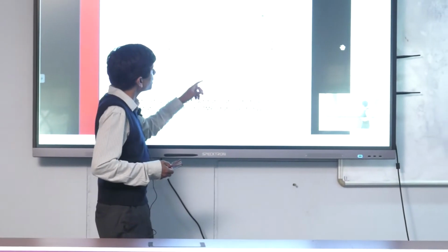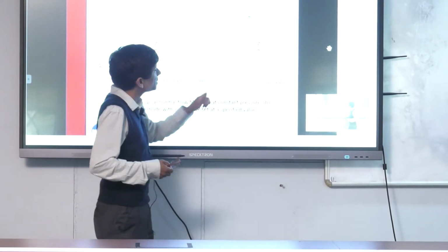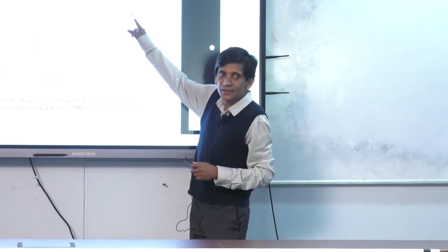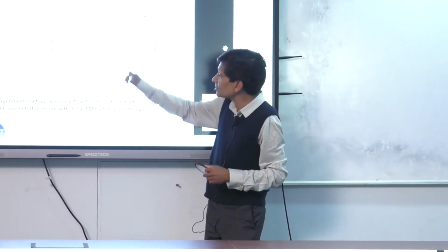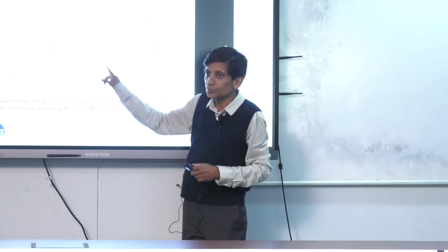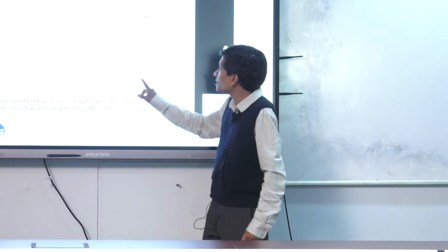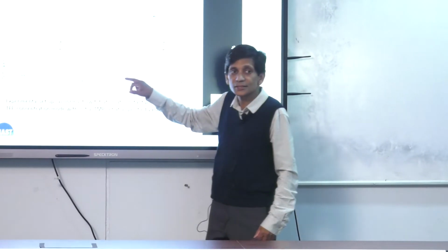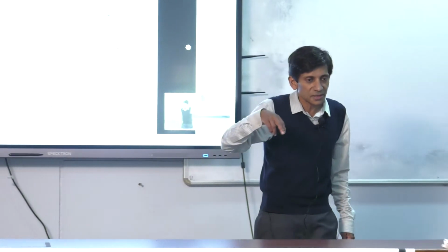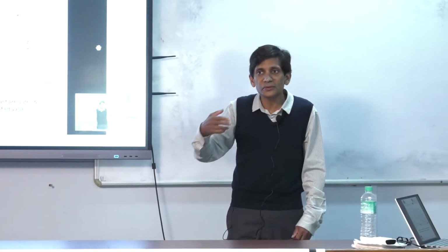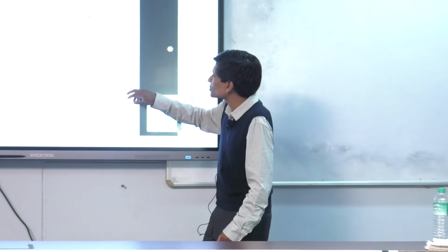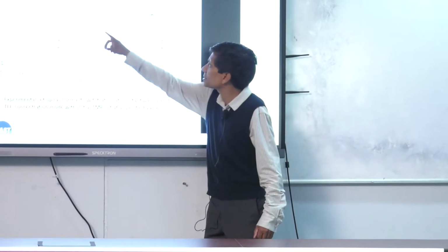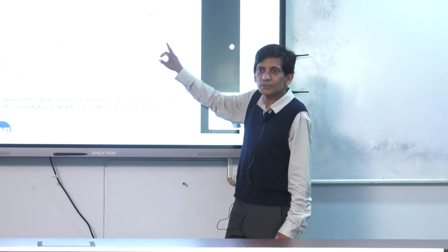And then we can also run it in tangential flow mode, as you can see here. But what we can do is we can do something interesting. We can put a valve here. So we can artificially change the resistance through this loop, right? If I put a valve here, I'm putting a restriction here, so there's going to be a greater resistance to flow in this loop, right? Even just qualitatively, if the fluid comes here, it has a choice. It can continue along this loop, or it can go through the membrane pores, right?